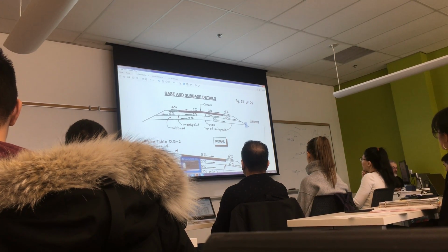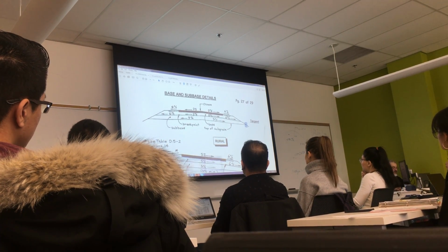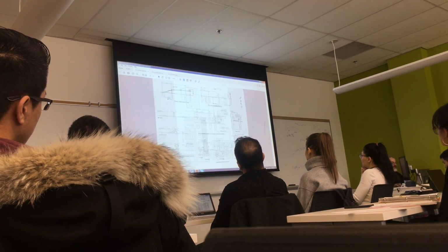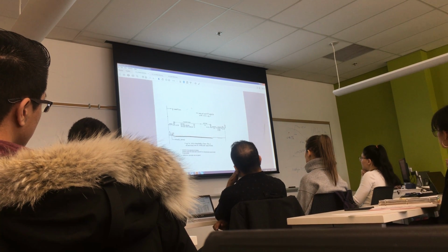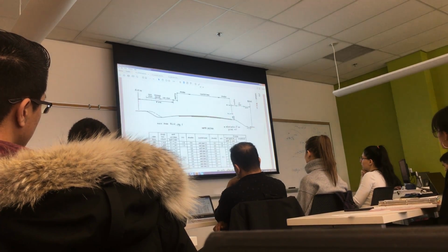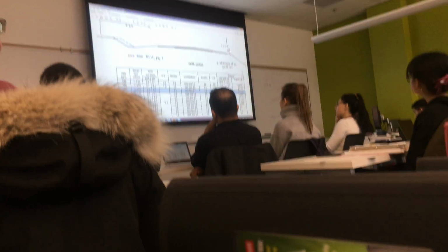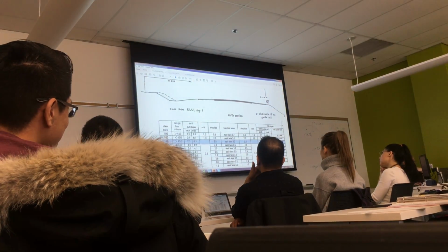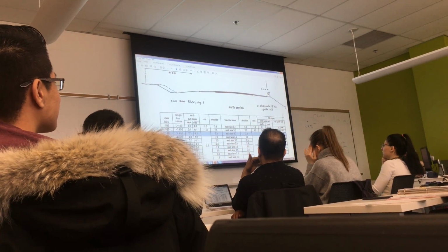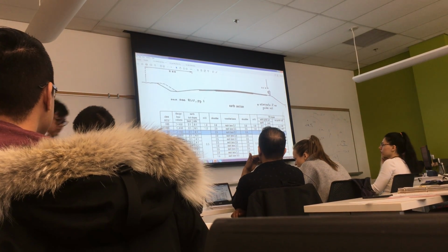So let's go back to the design requirements, so back to here, and then go back to the RCU. Right, and remember 90, greater than 450, we're looking at this. If it's a fill slope, use 6 to 1. If it's a cut slope, the side slope is also 6 to 1. So I'm going to come down from the center of the roadway, 6 to 1 on both sides, and see what happens.